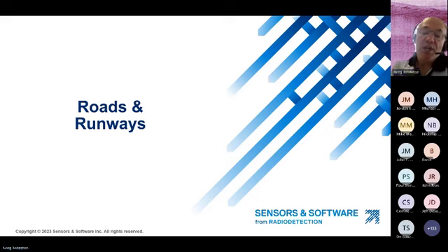However, using GPR on human infrastructure has a higher than average success rate. So GPR works well on concrete, as I've already mentioned. And my experience is that it often works well on man-made structures such as roads, bridges, and runways. Let's look at some examples of these applications.